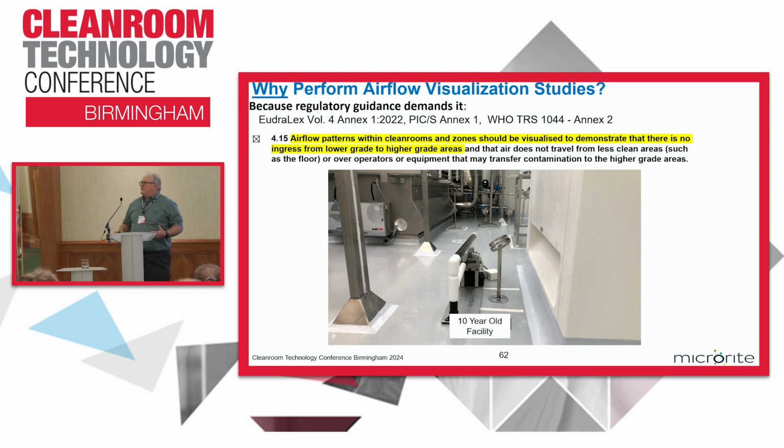The point being, if you take nothing else out of this presentation today, is particle counts, air velocity, air exchange rates, pressure differential, all those things are really important to qualify our clean room, but airflow visualization gives us a visual representation of the contamination control effect.